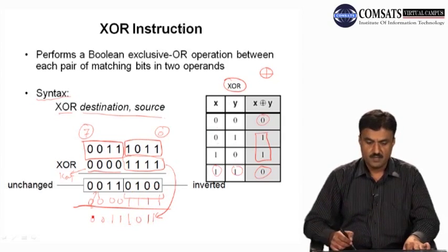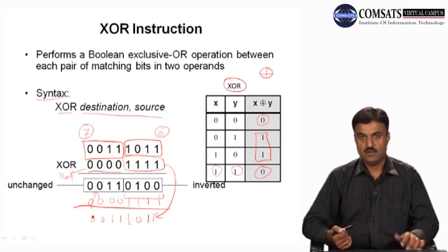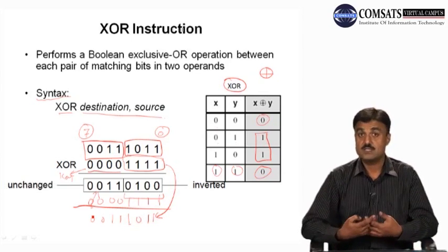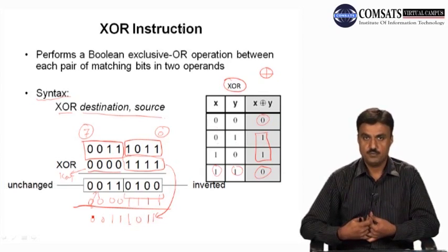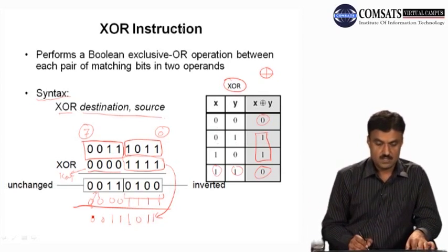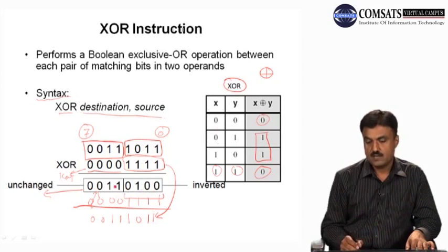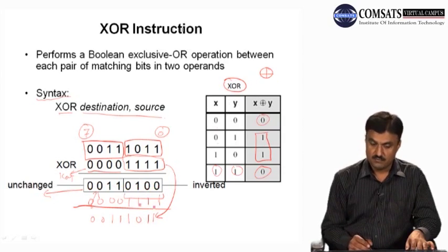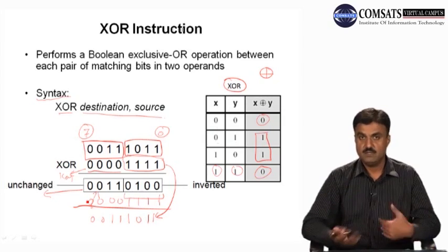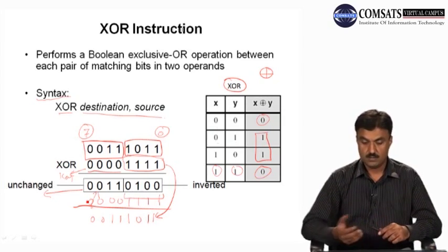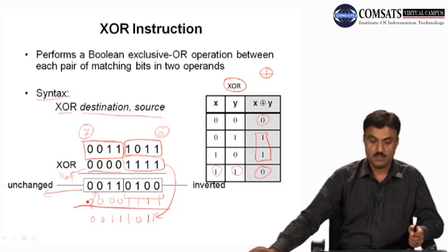So you can see, if we again perform exclusive OR with the same bit pattern, we will receive the same output. For example, this is the scrambled information, we scramble this one, nobody can understand what the original message or original information is, but if we again exclusive OR with the same bit pattern, we will receive the original information.